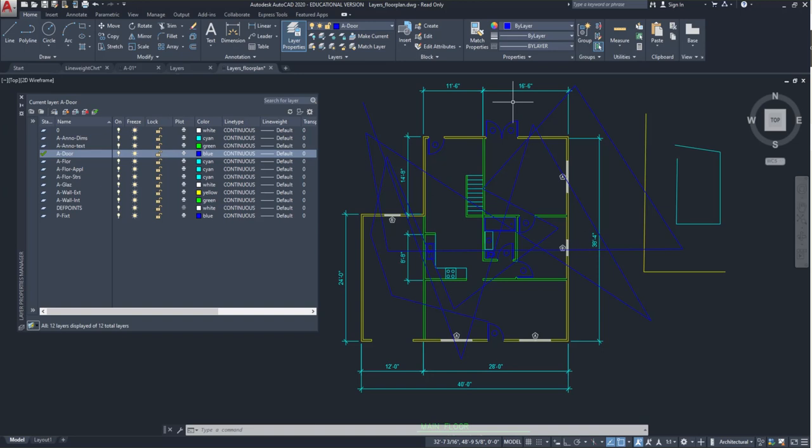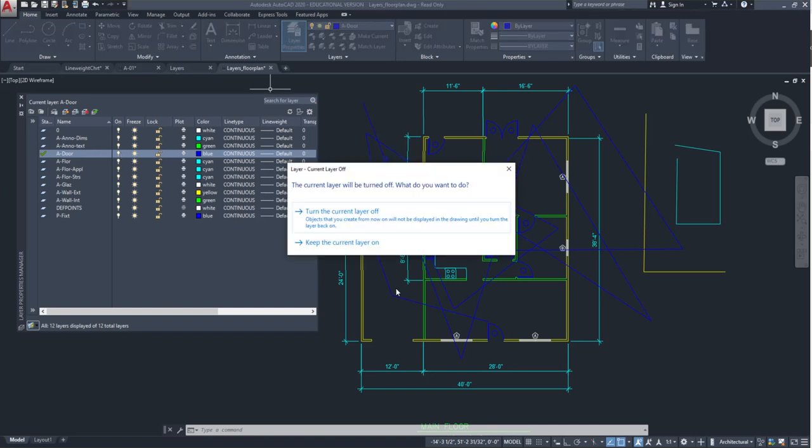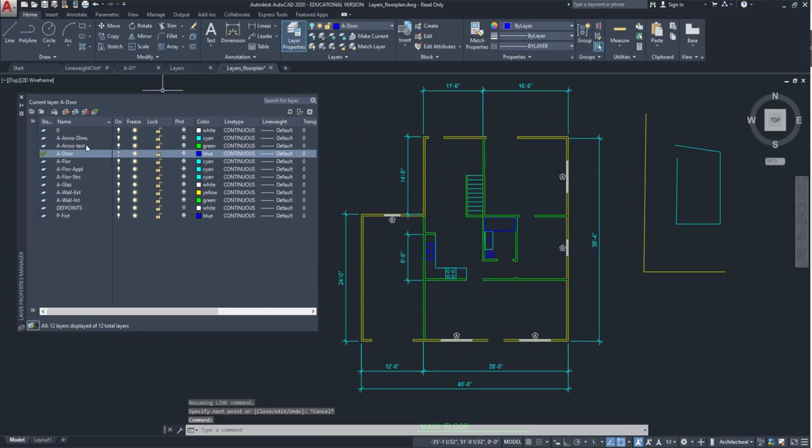And you think, well, even if I use it and I accidentally draw a line, well, I can delete it, right? Well, sure, but usually when you're making this error, you turn it off and then you forget that you've turned it off. And maybe you think you're drawing on a different layer. You hit line, you start drawing, you're like, hey, what's wrong? Oh, something's wrong. And you've already drawn 4 lines by the time you go back to investigate why your lines aren't visible on the screen. And at that point, you could either forget to delete them, or you could delete them but maybe leave one on the screen that you didn't see, right? And then somebody interprets that as something that shouldn't be there, okay? So using the on-off functionality will really set yourself up for error, okay?